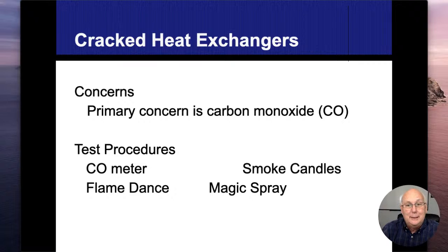And then the other one out here says flame dance. That one I'm not too comfortable with. I mean, you really have to have a big blast of air from that circulation fan blowing on the flame and causing it to flicker and move.